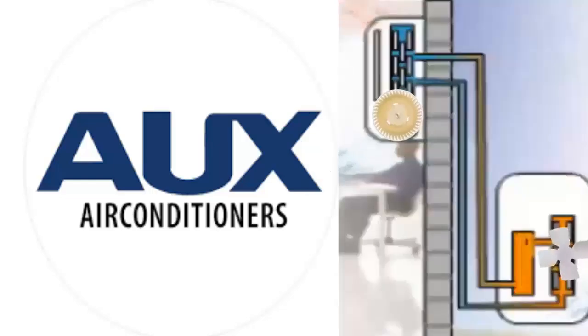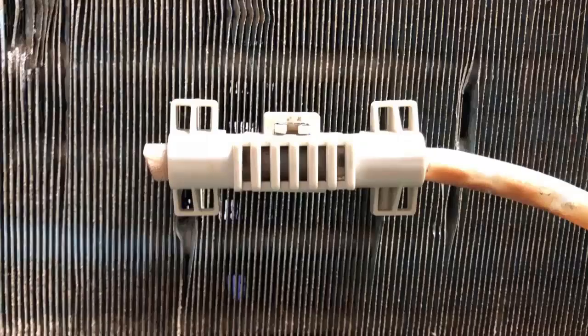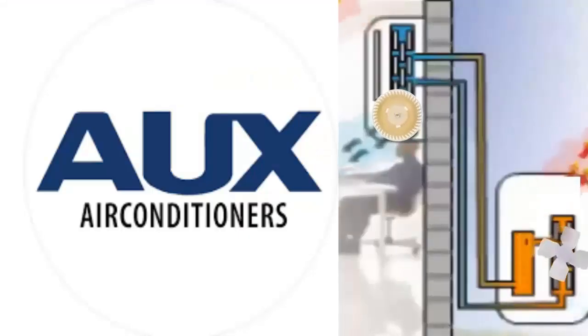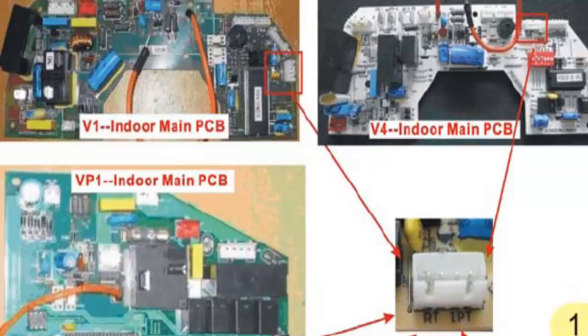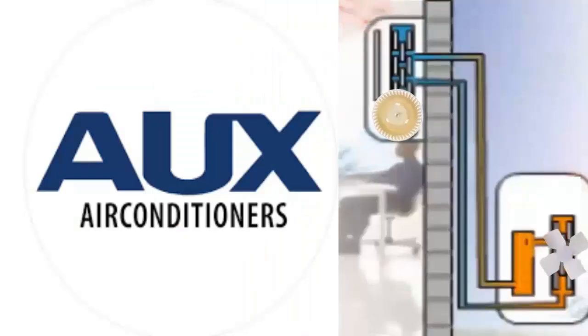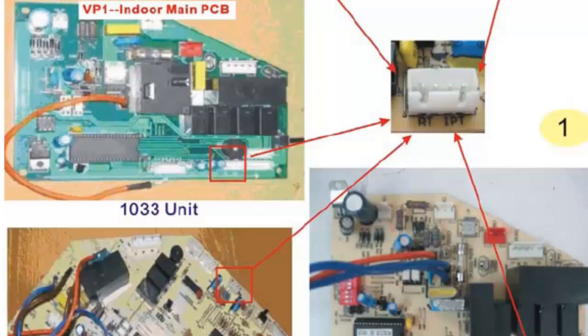3. Check the position of the sensor. Make sure the sensor is properly placed and securely fixed in its position. 4. Ensure the sensor's connections to the electronic control board are secure and that the wires are undamaged. 5. Disconnect and reconnect the sensor. Clean the connections if necessary.